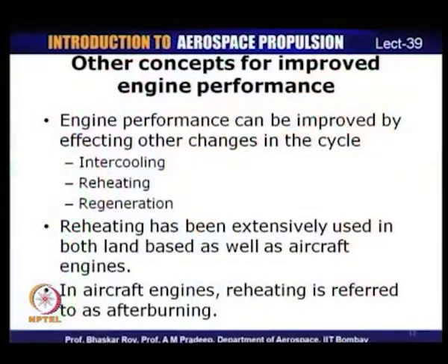So, reheating is one thing which has been commonly used, because it does not really require any additional complexities. It is just a tailpipe that is attached to the turbine exhaust before the nozzle. And so, in aircraft engines, reheating is usually referred to as afterburning, and they are used in land based engines for power generation, where you have different stages of turbine with reheating in between. In military aircraft engines, it is used at the exit of the turbine.